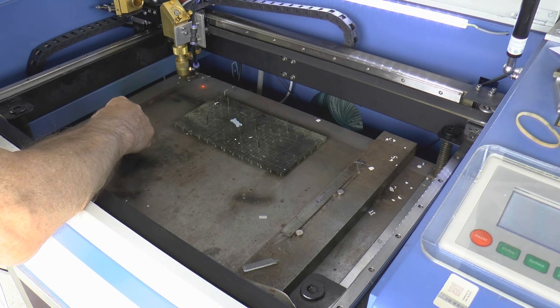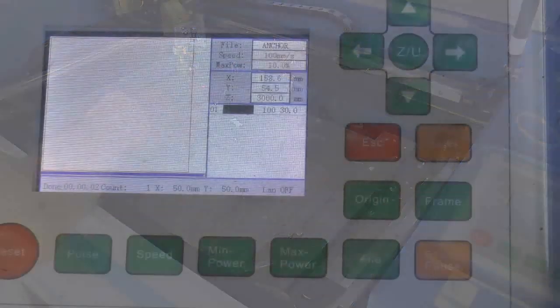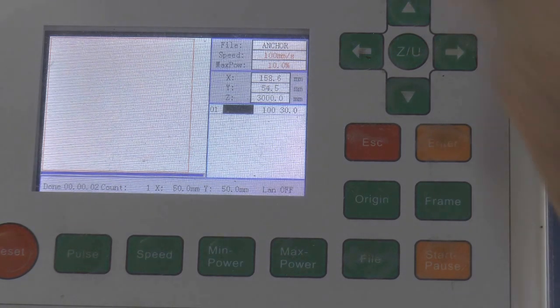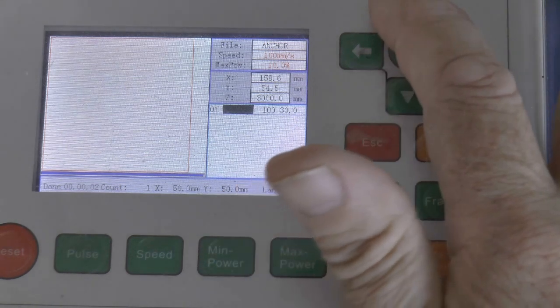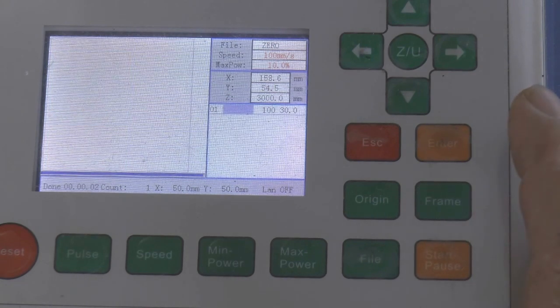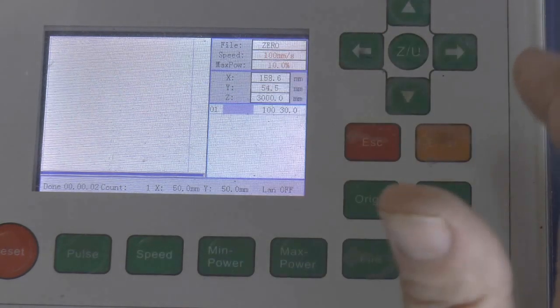Let's go and see whether or not our assumptions are correct. This is very much an egg on face job, because I'm going to demonstrate to you now the 4 positions that I was talking about. Now, the first position I was going to talk about was the absolute 0 position. As far as I could work out from the manual, absolute position meant that the program would run from machine 00. Here's my program that I've written in here.